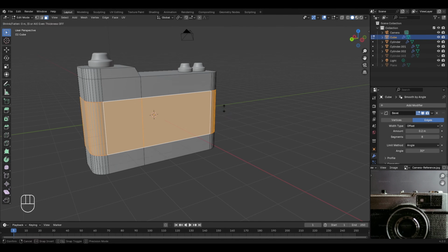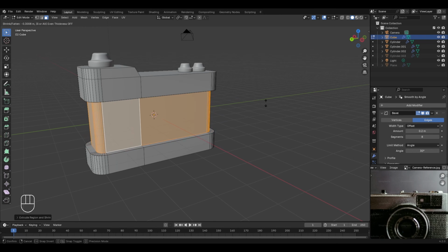normals. So I'll select this, and if I move my cursor away, then you will notice that the extrusion effect is now being applied to all the faces that we have selected, and since the name of this tool is extrude faces along normals, as a result, all the faces are getting extruded along their respective normals. So once you have adjusted the size of extrusion, simply left click to finalize, and if I return back to